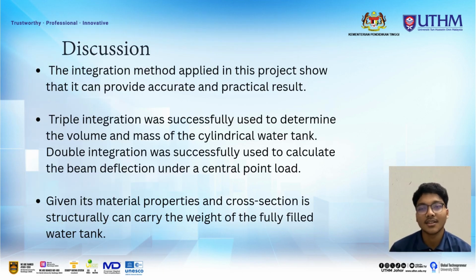In discussion, the integration methods applied in this project have shown that they can produce accurate and practical results for real engineering problems. We successfully used triple integration to calculate the volume and mass of the cylindrical water tank by applying cylindrical coordinates. This allows us to model the tank shape accurately in 3 dimensions. At the same time, double integration was effectively used to determine the beam deflection under a center point load.